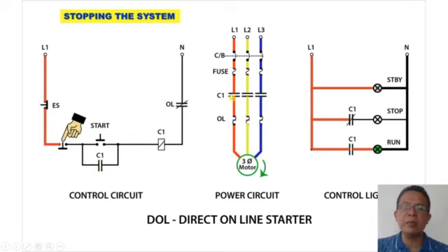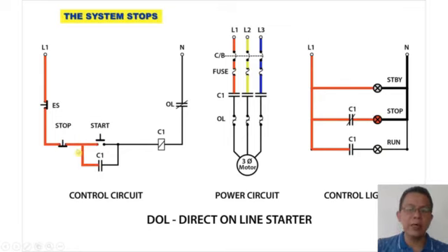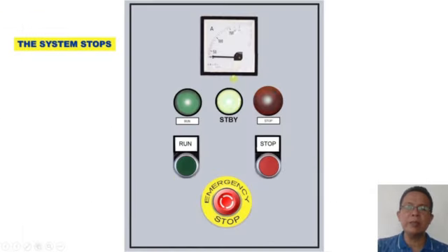The main contact, which was closed before, is now open because we de-energized the contactor coil. So the main contact is open, and we interrupted the flow of current. The pilot light here only interchanges from run to stop. I take my finger off and the system is stopped. What we see now is the load meter stopped.